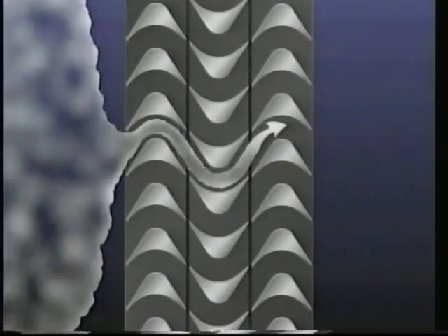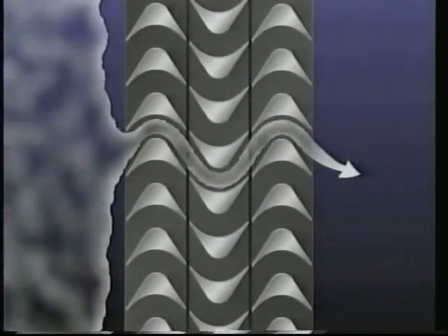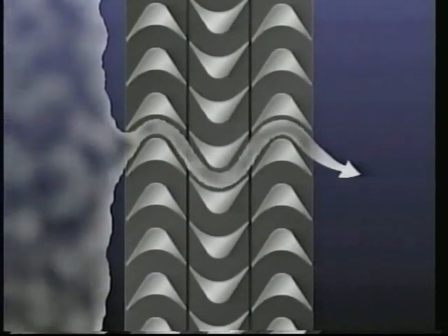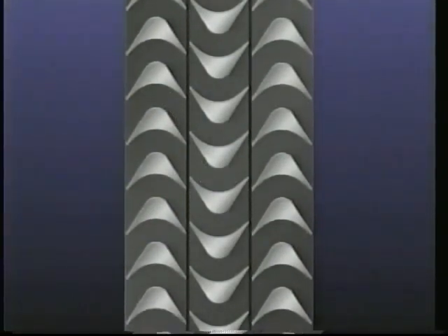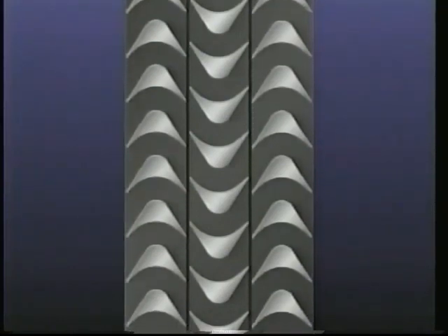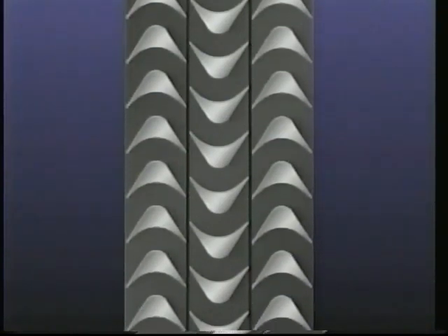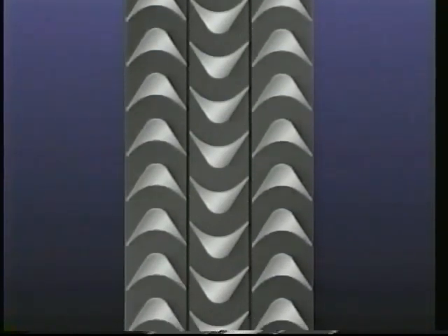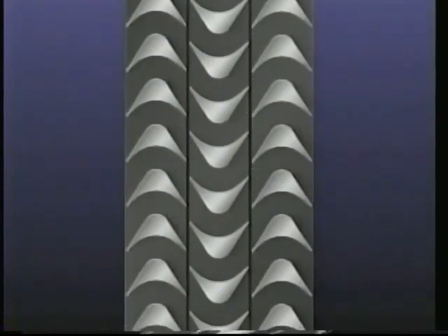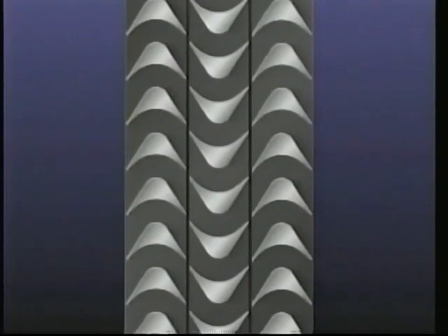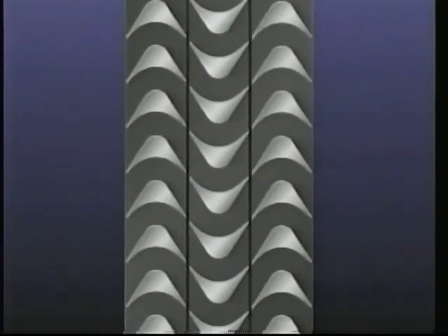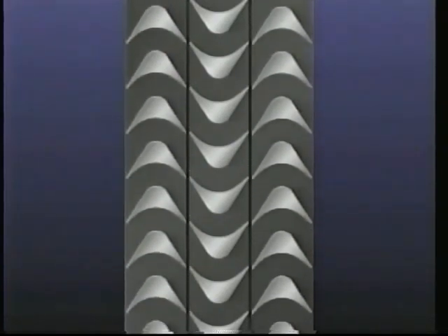Once the steam has passed through the second set of moving blades, the steam is routed out of the turbine. This flow path of steam striking the moving blades causes the moving blades and the turbine shaft they're mounted on to rotate. The energy in the steam decreases as it is converted to rotational force. So the steam now contains much less energy than it did when it entered the turbine.